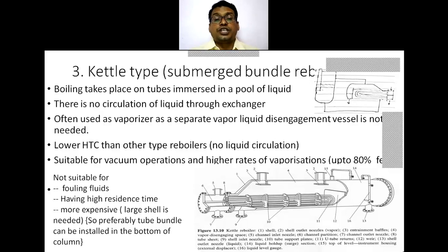So the fluids which do not produce fouling are preferred in the case of the kettle type. Then it is not suitable for high residence time. The temperature may degrade the bottom product, and as a result we are restricting high residence time fluids.